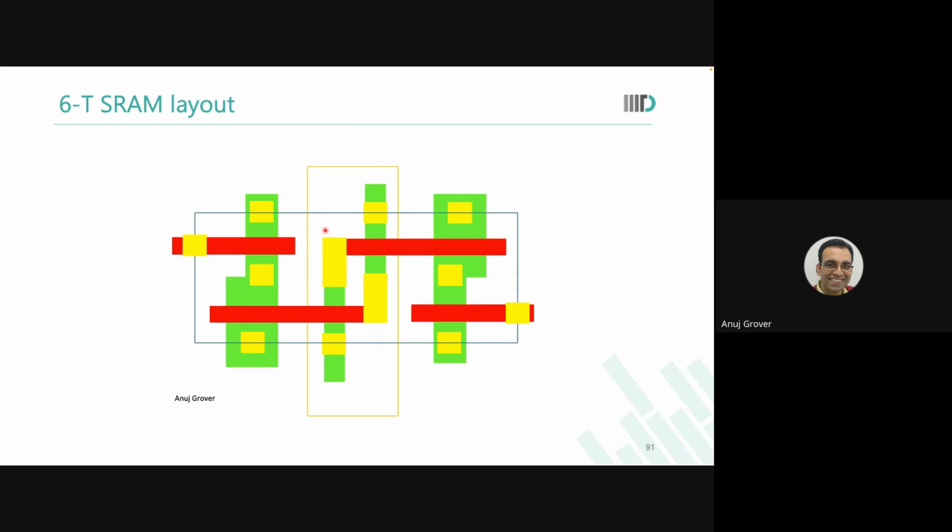Now, why can't such a long contact then be allowed when you're putting multiple contacts on a big device? No, no, no. We're giving you a finger, don't grab the whole arm. We're giving you this concession because for you area is diamond. Making a long contact still requires optimization in the technology. A lot of OPC is required to be able to make this. So we are doing this because for you area is really that critical, but we can't do it for everyone.